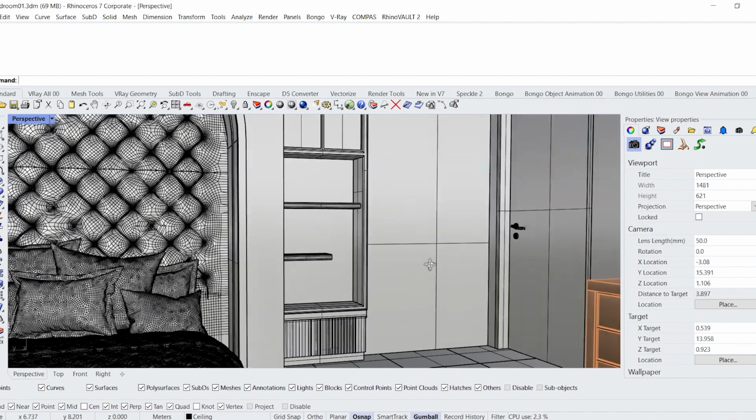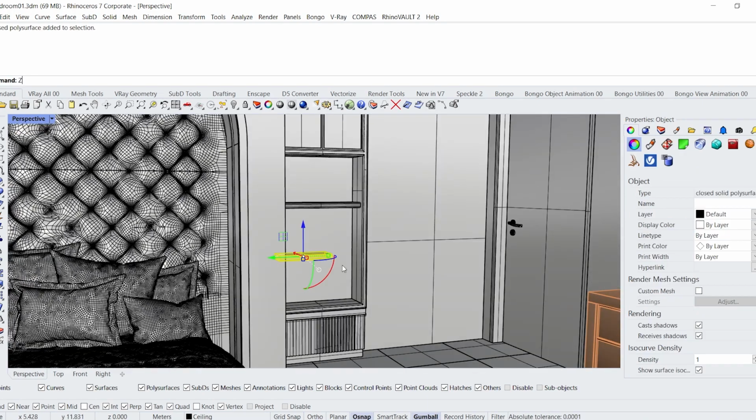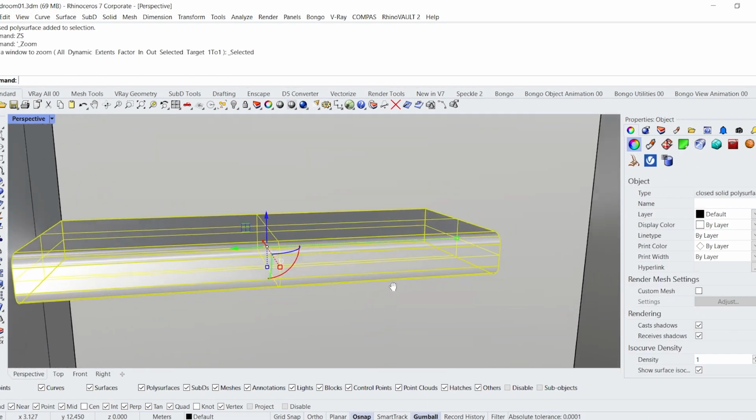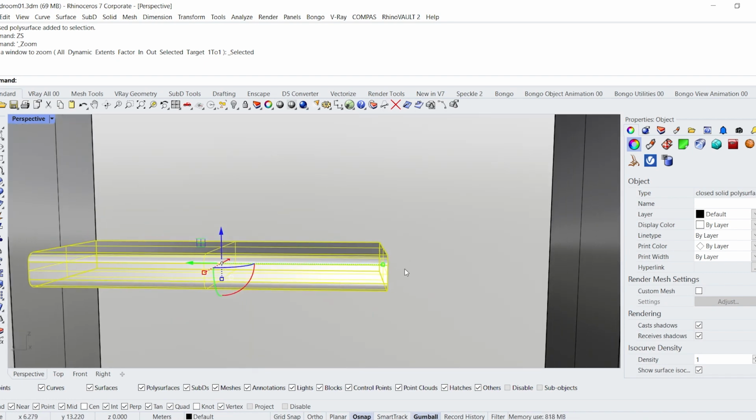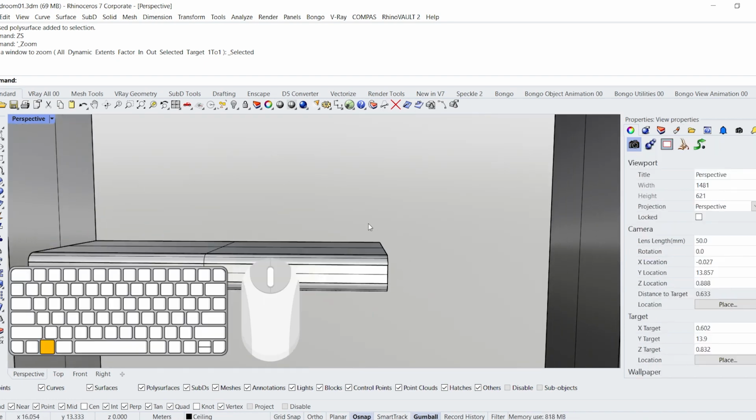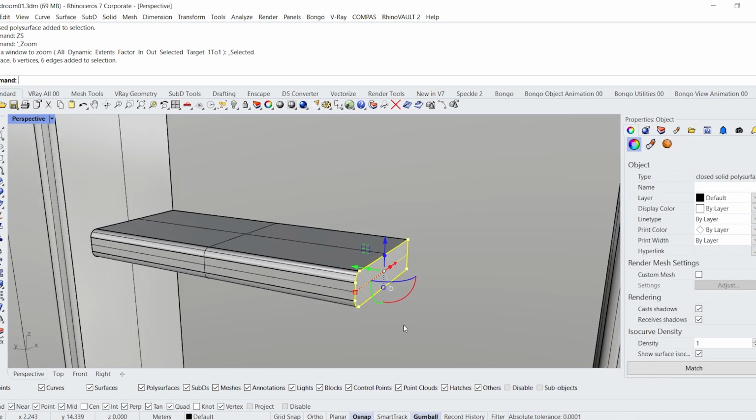Number 9. Isolate lock. In this scene, I need to extend the shelf and close the gap with subselection. First, I will show you the advanced technique. Hold Alt and click near the shelf, but not on it. Then hold the left click. Release Alt while holding the left click. And finally, hold Ctrl plus Shift and drag to create a rectangular subselection.